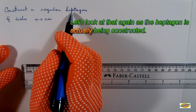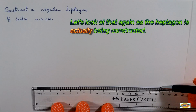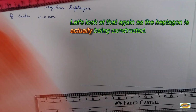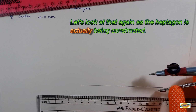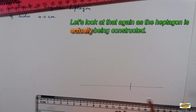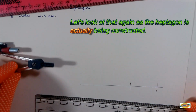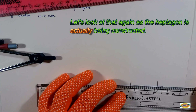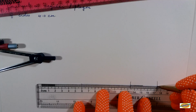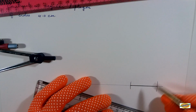Construct a regular heptagon of sides 4.0 centimeters. A construction line, measure 4.0 centimeters. From near this end, you can arc like that. Change over here, make an arc like that, bold that piece of the line. Next thing we want a perpendicular bisector at this point.